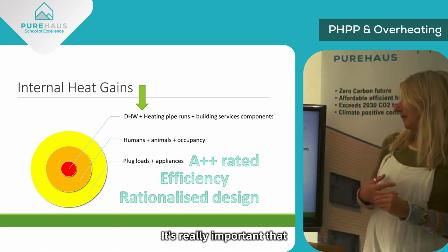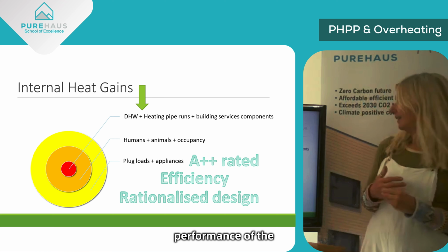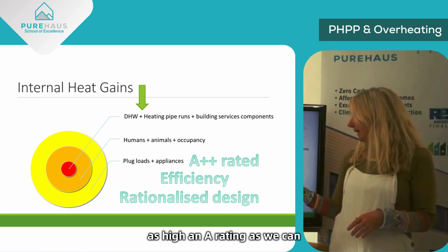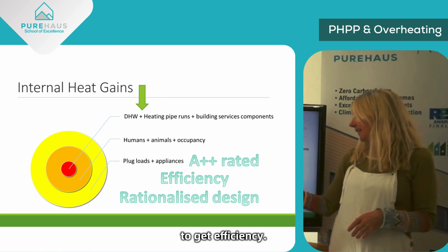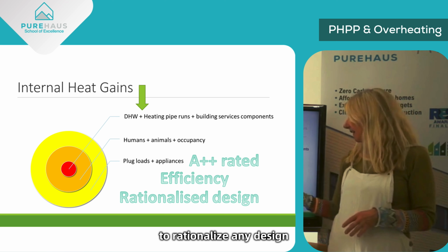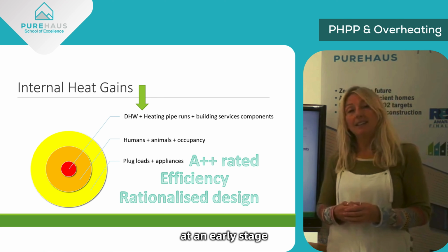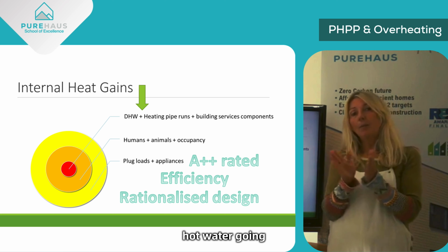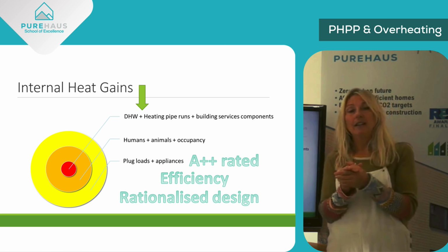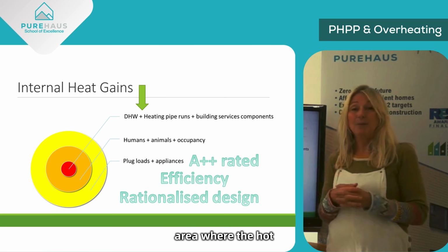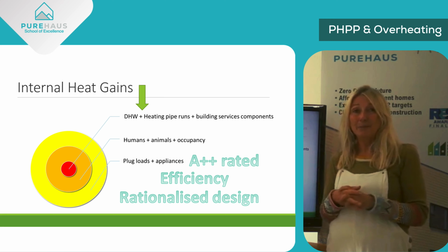It's really important that we consider the performance of the appliances, going for as high an A rating as we can to get efficiency. And also to rationalize any design at an early stage so we don't have very long runs of hot water going through the building from the source to a particular area where the hot water is needed, for example.